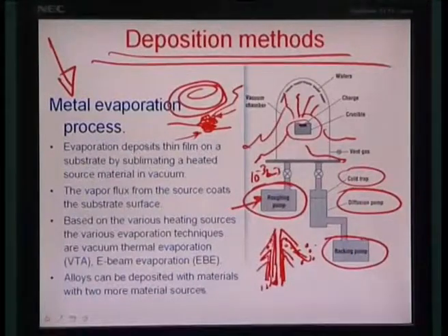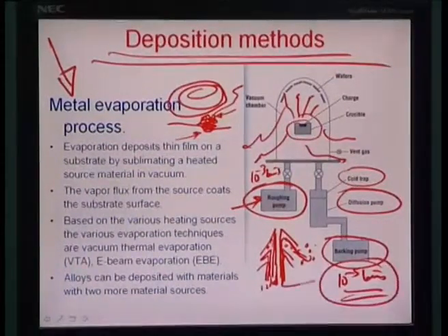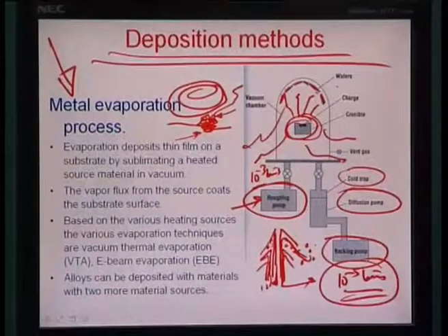So therefore it can attain a finer vacuum level of, let us say, about 10 to the power -5 torrs or so, and in this vacuum it is sufficient to create a clean process where there is no oxygen or nitrogen inclusion within the silicon. The substrates really are mounted on the top. As you can see, there is a series of substrates here which are rounded off and just over the target in the vacuum chamber, and these wafers are deposited with the metal on the top, and you can use a sacrificial layer in photolithography so that the deposition happens in a normal way.